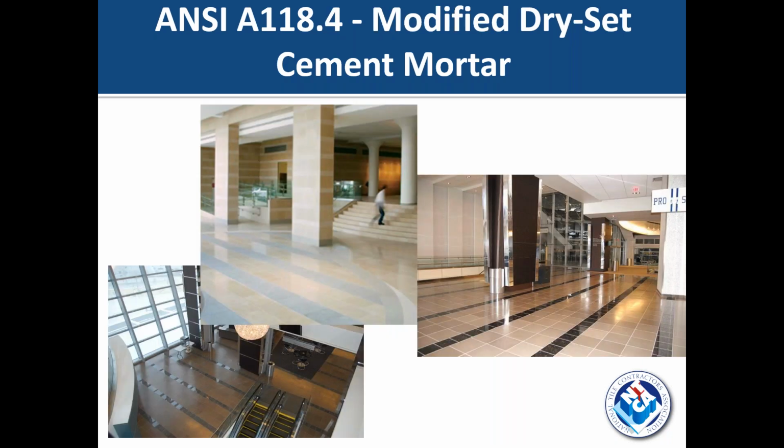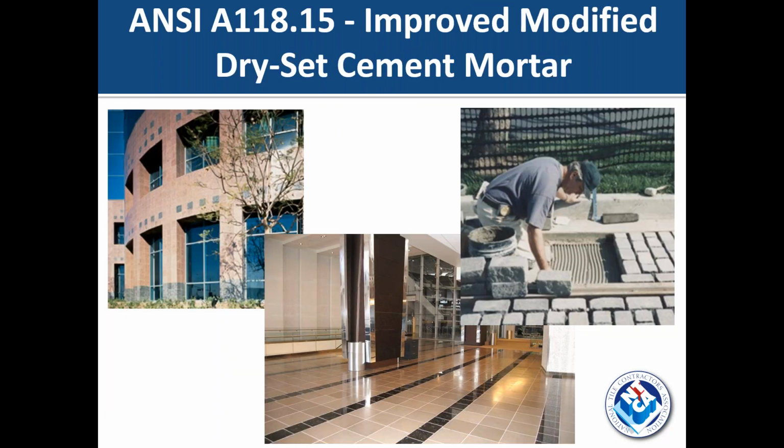Followed by ANSI A118.4. Now this is the original standard for a modified dry set cement mortar. And as I said earlier, these products, the modified ones, can go over a much greater variety of substrates, more challenging substrates, used with porcelain tile, etc., and used in exterior applications. And finally, the newest standard, which is ANSI A118.15.